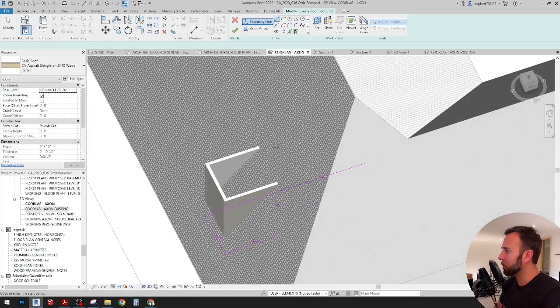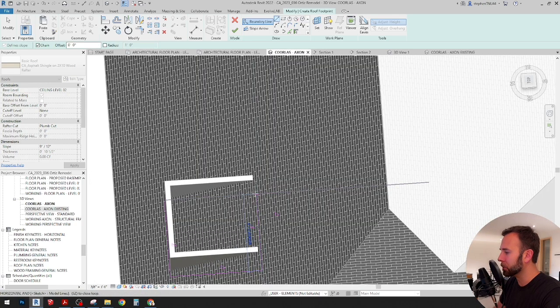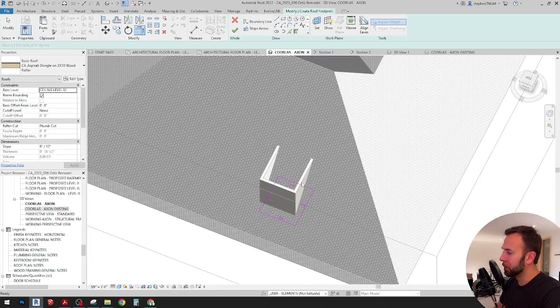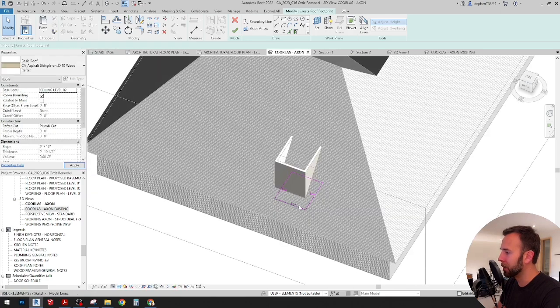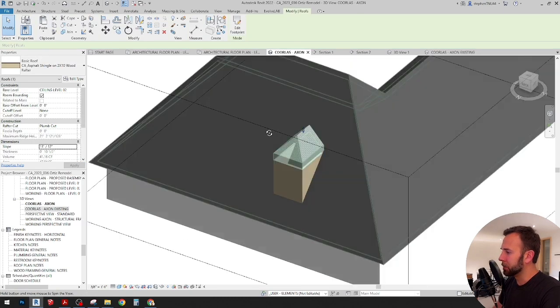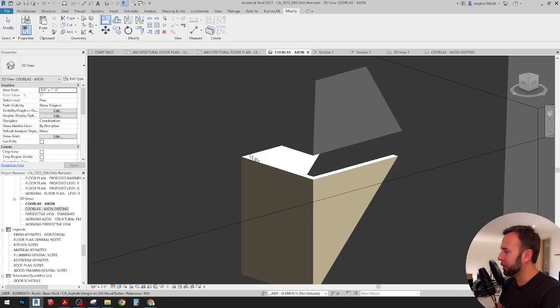and for dormer roofs, I believe you can just close it off, and then there's another tool to snap it shut or snap it against the existing roof there. So I know this one I don't want to have a slope, so I'm going to remove the defined slope character from that parameter. And let's give this a try, it should also match 13/12. And that looks okay. We're doing the plumb cut on these and snapping it to the base.